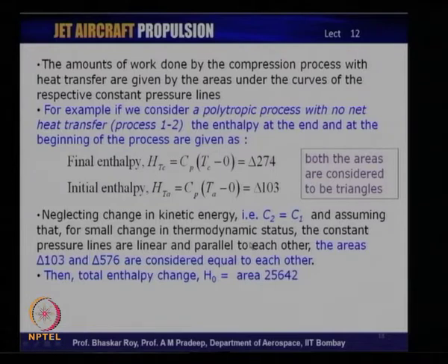So, this is what we learn from simple thermodynamic analysis, that you can use thermodynamics as a matrix to figure out what is going on in the compression process, and then see whether you can get your compression process done a little more efficiently, a little more effectively, so that it serves the purpose of the jet engine and brings the jet engine closer to the ideal Brayton cycle, which is the matrix on which the jet engine is functioning. So, this is what we have done in today's class, the thermodynamics of the compression process, and we can see that cooled thermodynamic compression can give us some benefits.